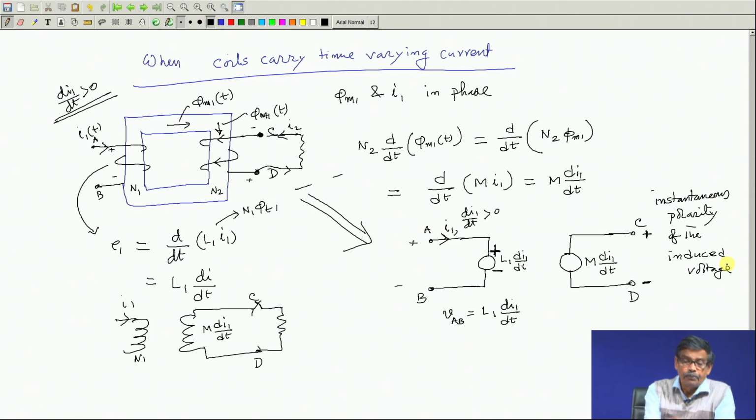Now, one important thing you just try to understand. This I remove. Even if you do not connect that load, while arguing to decide upon the polarity, imagine there is some current here in this direction, which will ensure this is plus, then you can come to the same conclusion. But what I am trying to tell is that if in this diagram the core is drawn and then the coils are drawn with their senses, in which sense the coils are wound, you can easily understand.